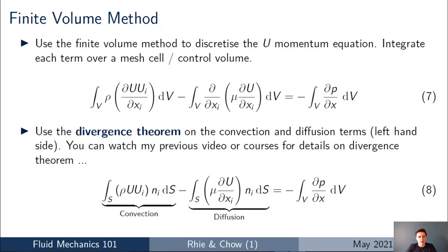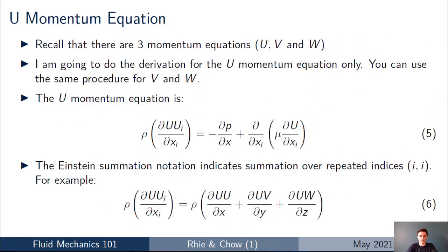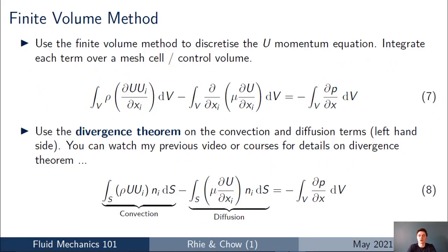And the way we're going to proceed is now we need to discretize this partial differential equation. And the way we do that in CFD nowadays is most often using the finite volume method. And for the finite volume method, what we do is we consider a single cell in our mesh. So if you think of your computational mesh that you've made for your CFD calculation, we're considering a single cell in that mesh. And the cell could have any shape, any size, and be anywhere.